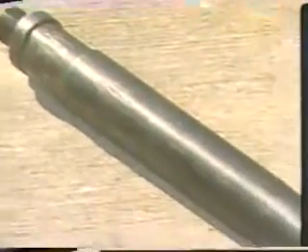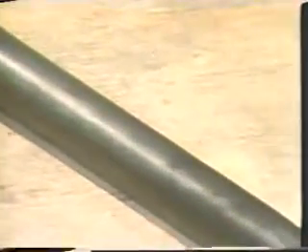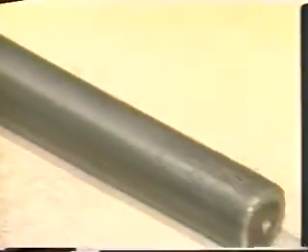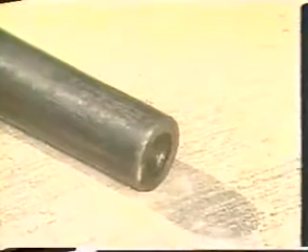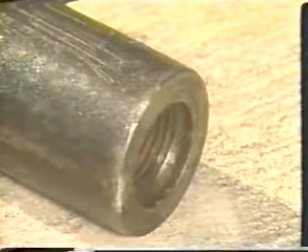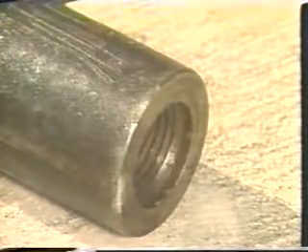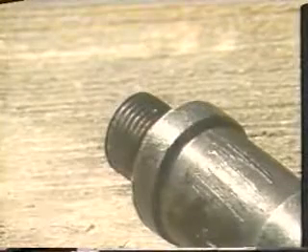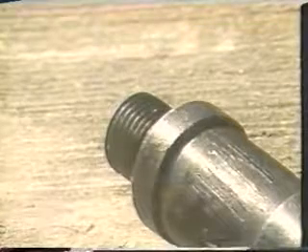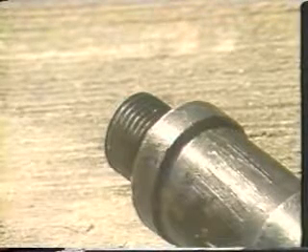The stem provides the mass required for jarring operations and to carry the tools into the well. By adding or removing stem sections from the tool string, the wireline specialist can control the force of the impact being delivered downhole. The size and type of stem used is determined by the size of the tubing bore, the operation to be performed, and the amount of lubricator that can be raised over the well.